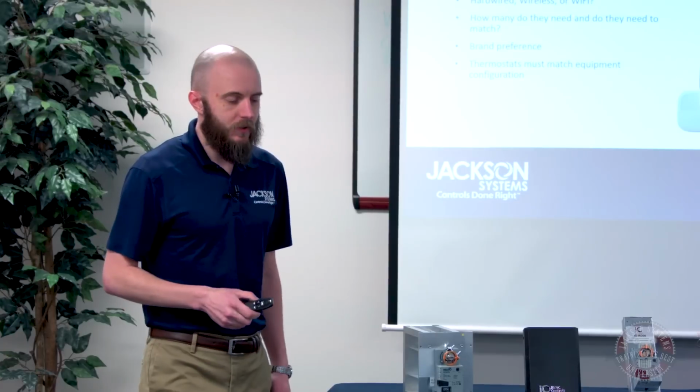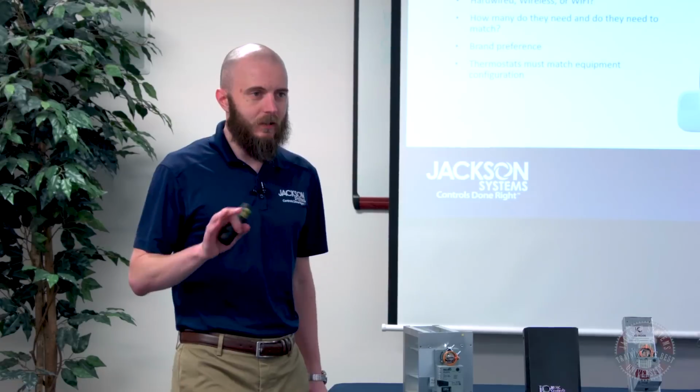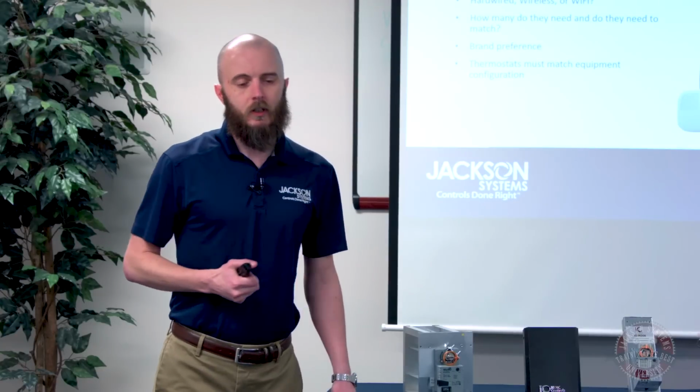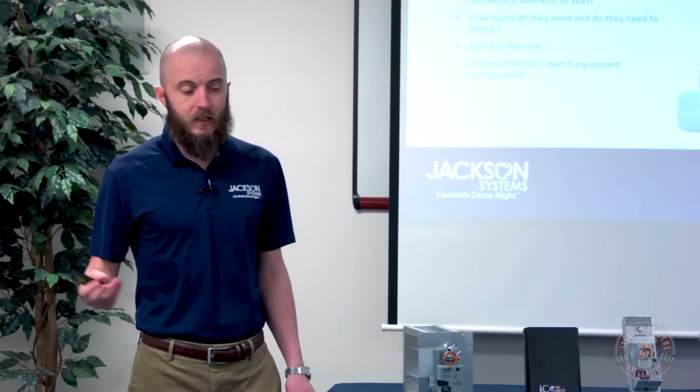Beyond that, I would try to set it up so that the bypass damper wouldn't react until the ECM blower has basically done all it can do, right? So when the ECM blower gets to about as far as it can go, only then would the bypass damper start to open up. That would be a little bit different setup than we normally would do on a bypass damper, because normally we want the bypass damper to just start opening as soon as the zones start closing. So that'd be a little bit more of a nuanced setup. But generally we want the ECM blower to do its thing, and then after that, if there's additional static pressure to be relieved, we would set the bypass damper to begin bleeding at that point.